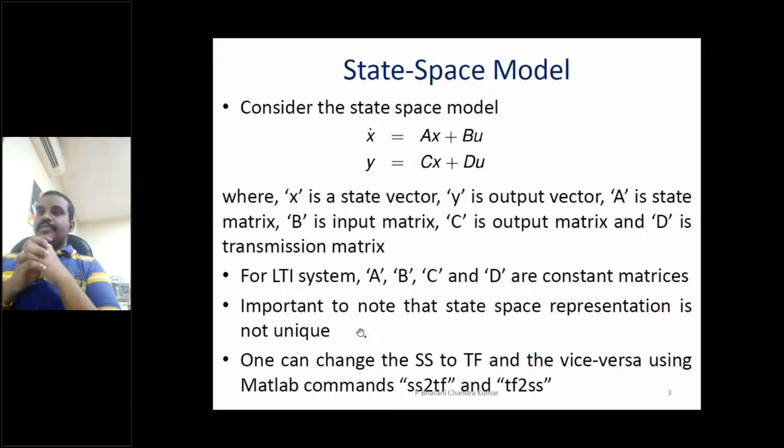Whatever the form, if you convert your system back to the transfer function, you should get the same transfer function. That means the state space approach is not unique, but the transfer function is unique. One can change state space to transfer function and vice versa. Manually you can do it in different ways, or using the MATLAB commands ss2tf and tf2ss.